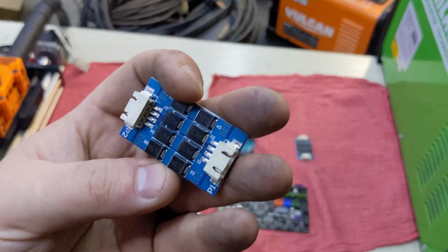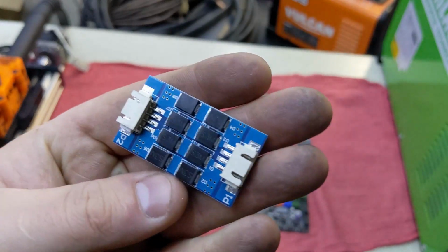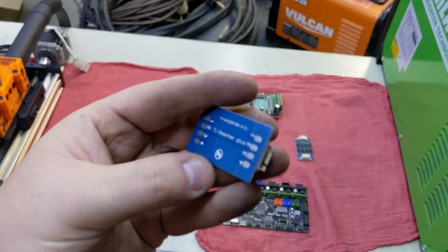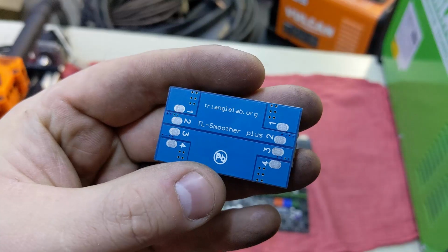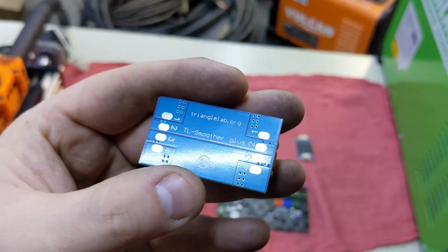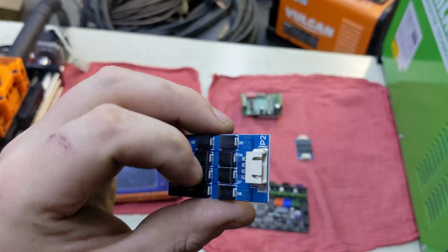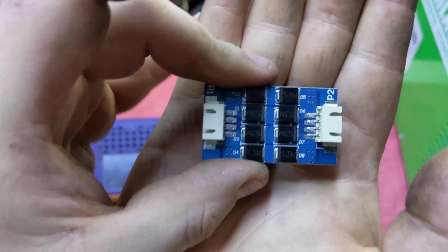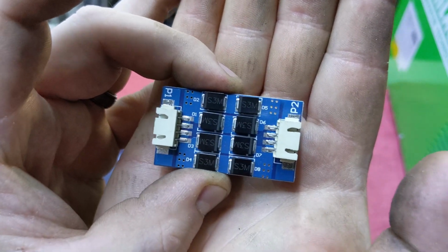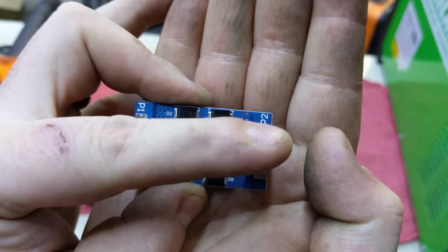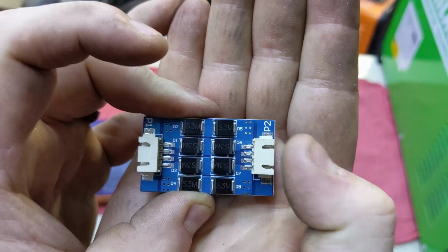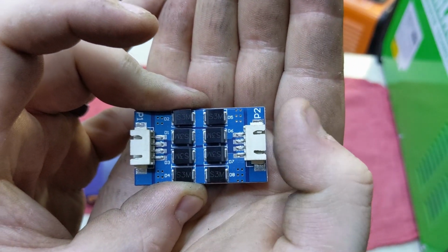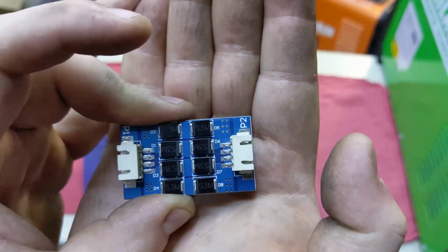I would suggest, and now I have not tried this, you may want to look into some of these little boards here by Triangle Lab. These are called TL smoothers. What they have is a set of diodes on this board that only allow electricity to go one direction across this board, unless it's like crazy high voltages, like 50,000 volts, something like that. So it produces a little bit of heat, and there's a heat sink that comes along with this board.